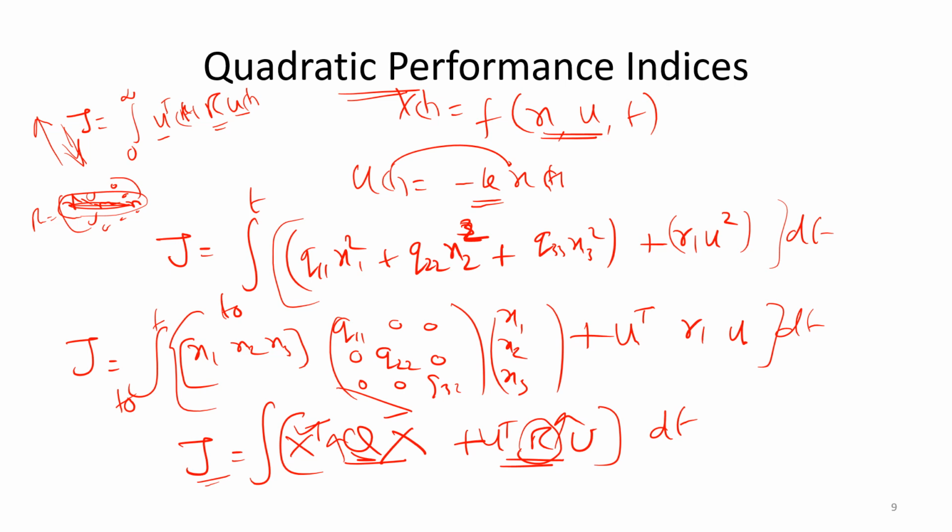It depends on whether you want to increase J or decrease J. So first fix the criteria, fix the performance indices, like minimum ISE, minimum settling time, minimal overshoot, or maximize the profit or the efficiency. Then measure the state variables and the control variables, and in between insert one matrix.